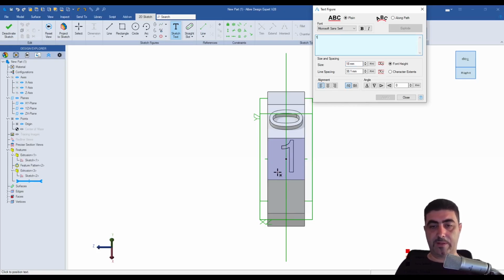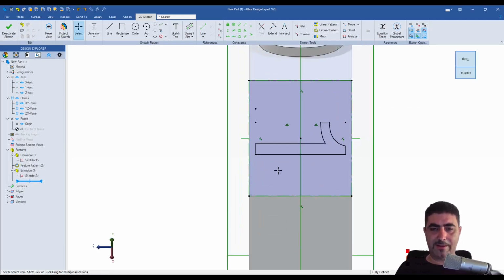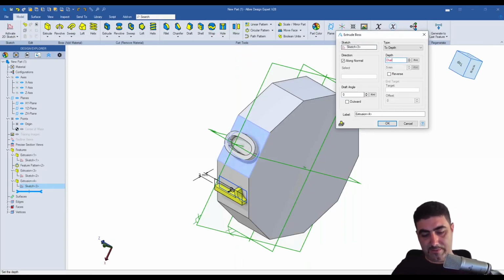And well, how do I make it be the same orientation as 0? Well, this looks nice. Okay, so I'll just put it somewhere up here. I'm imprinting this face. I'm going like so. Now that I look at it, the origin point that Alibre gives you is perfectly reasonable. You don't need to use the midpoint constraint. But anyway, then I will extrude this character depth, and I also am going to select this and copy it.